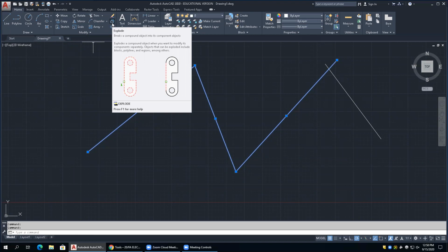And it's kind of neat. All right. So if you have a polyline, remember, and you explode it and it's got width, it'll lose the width. Okay. But once you convert it back into a polyline, then you can give it width. Okay. So those are all nice options. Everybody getting that one? Pretty cool.